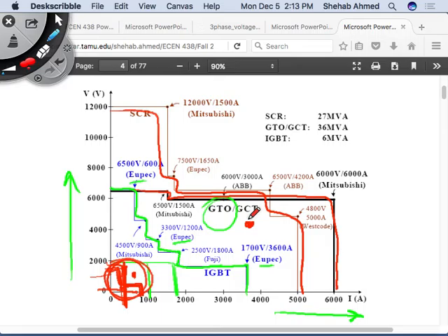Because with multi-level topologies, what was the benefit versus the classical H-bridge or three-phase inverter, single level? What's the benefit that we get, besides improved waveform quality? What was the benefit on the switch voltage rating? Yeah, it was half for the three-level inverter, and then it became 1/4. Depending on how many levels you add, the voltage rating becomes less and less, right?